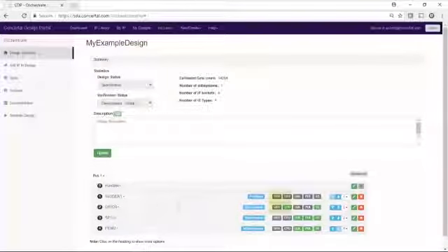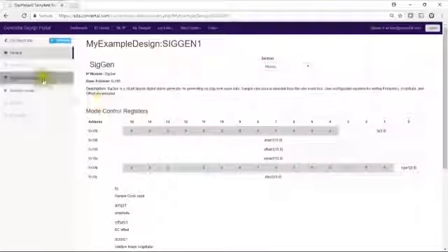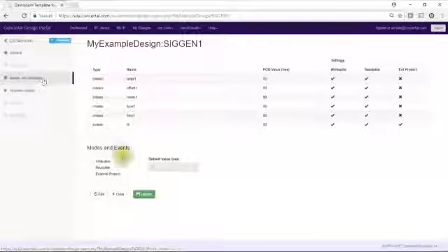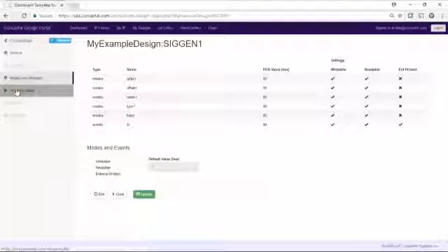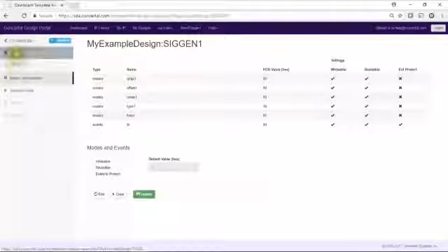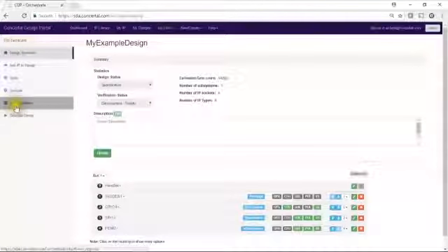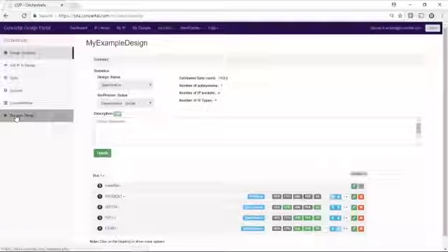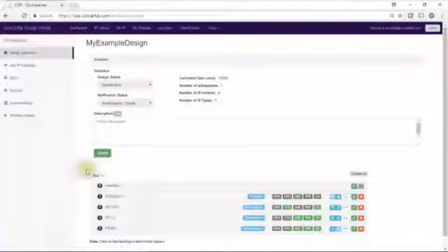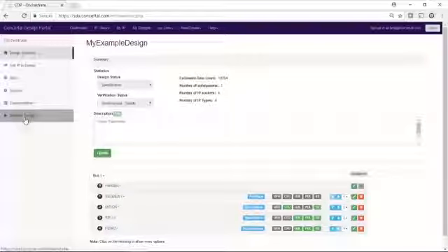Now, we can go and actually begin to edit the properties of these IPs. If we don't specify anything, we can go right into Simulate Design, build the part, and the design that's generated will be a highly configurable design. Since we haven't defined the relationships in the database, it will assume that it needs the flexibility of allowing any input to any IP to be driven by any output of any other IP.